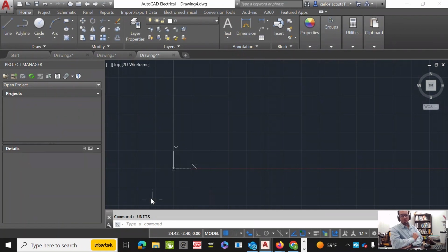Now, tolerance, I said precision is not the same as tolerance. Tolerance is a manufacturing concept. It's when you have your part that says 3.25 inches long. When you take it to a place that is going to manufacture it for you, they're going to have to make sure that it's 3.25, but it's going to be expensive. So it's going to be less expensive if you say, okay, this is 3.25 plus minus a tenth of an inch. So just set your machine to do this at these tolerances. As long as you meet that, I'm happy.